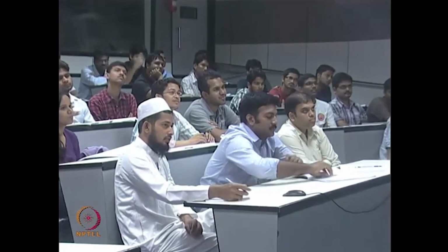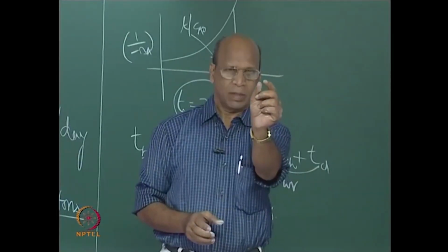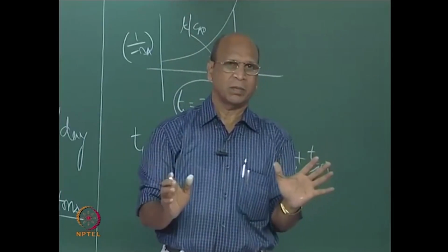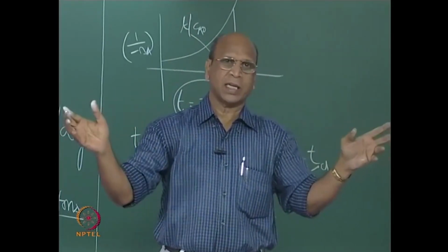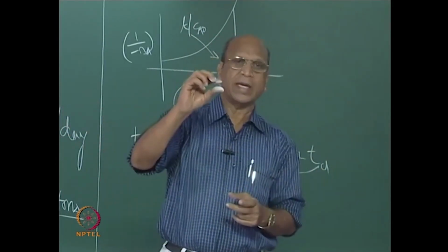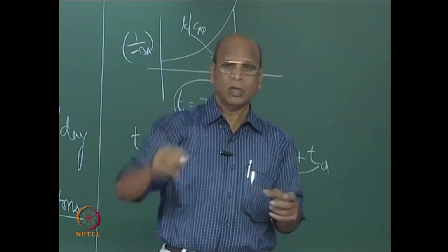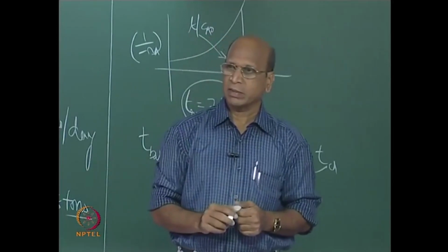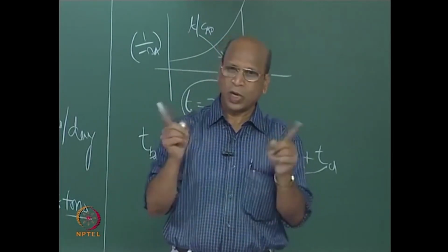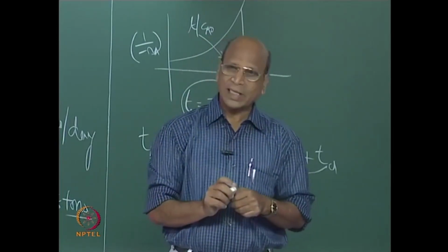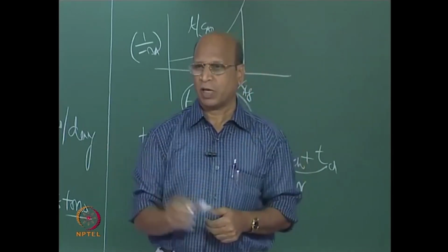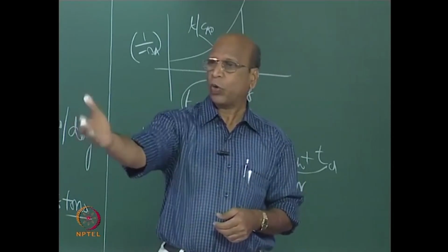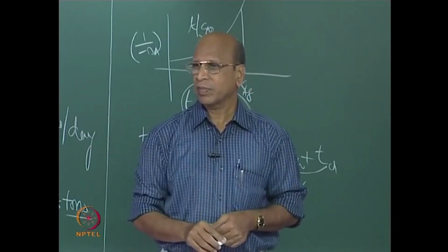I told you two extremes. You can take 1 nanometer, almost 0, and then calculate the length. Not practical. You can take the diameter of the earth as your tank diameter and then also calculate the height. That is also 0. So these two are not engineering solutions. So what is the engineering solution for fixing L by D? He says 0.75, you say 2. Why do you say 2? I will also ask him.